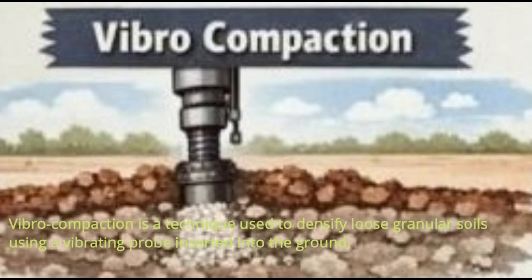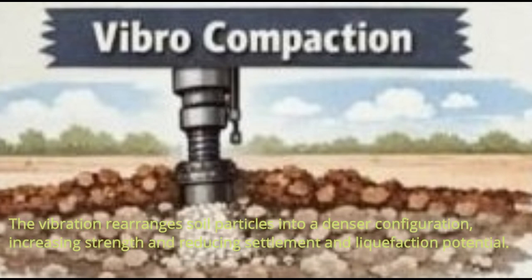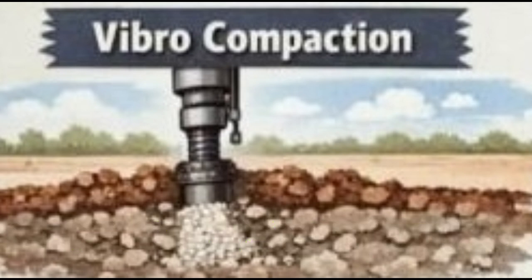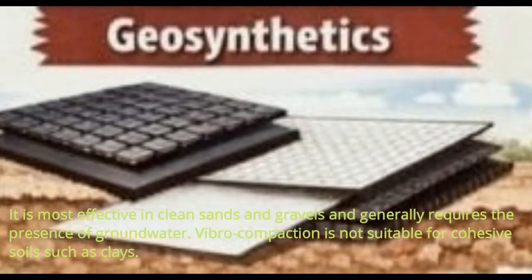Vibrocompaction is a technique used to densify loose granular soils using a vibrating probe inserted into the ground. The vibration rearranges soil particles into a denser configuration, increasing strength and reducing settlement and liquefaction potential. It is most effective in clean sands and gravels and generally requires the presence of groundwater. Vibrocompaction is not suitable for cohesive soils such as clays.